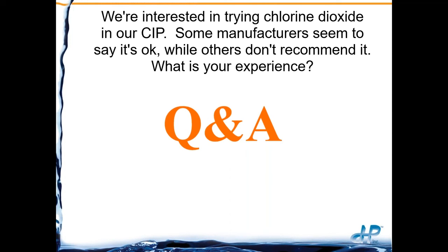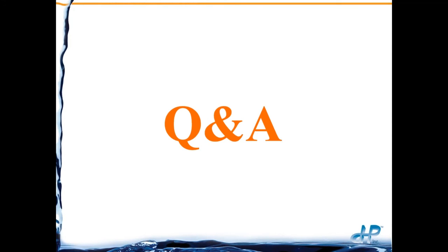David H. Paul Incorporated has no experience with chlorine dioxide coming in contact with RO membranes. But what we have read about is that chlorine dioxide can be used on RO membranes. I've heard as high as 200 parts per million of chlorine dioxide can come in contact with it. I would recommend getting in touch with the manufacturers of the chlorine dioxide units, or you can even buy liquid chlorine dioxide now and have it shipped in, although it can degrade rather quickly. So check on that, and what we find, you should be able to do it. Do your homework first, though.